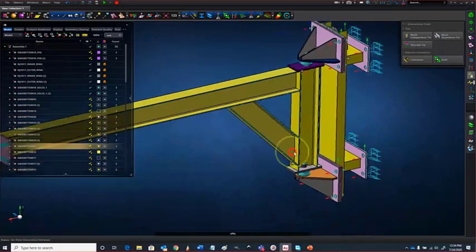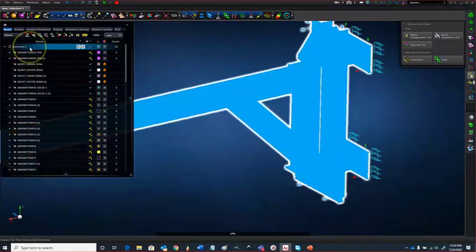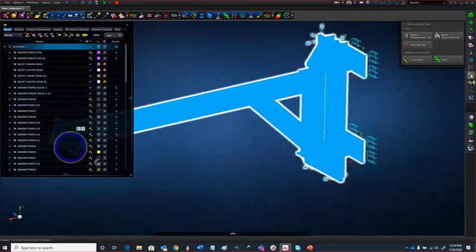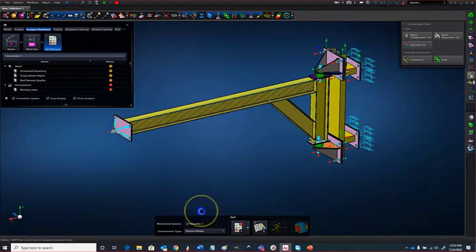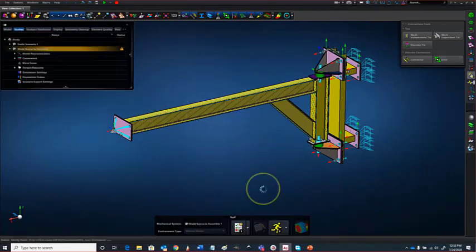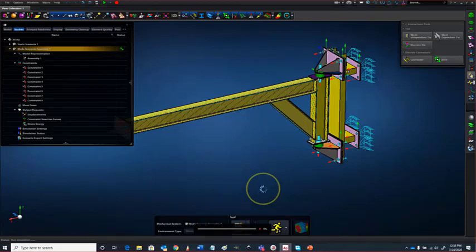And to check that everything was corrected perfectly, let's put it in an analysis scene, but set up a modal analysis to check the modes. And this should run fairly quickly. We can actually check exactly how long the analysis takes afterwards by opening up the simulation status tab over here. If you open it up before running the simulation, it actually updates in front of you, but once the simulation is running, you just have to wait for it.